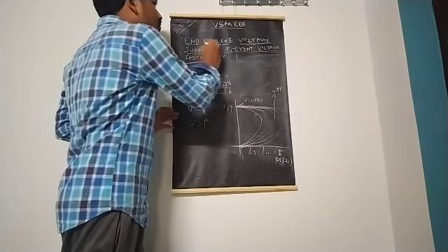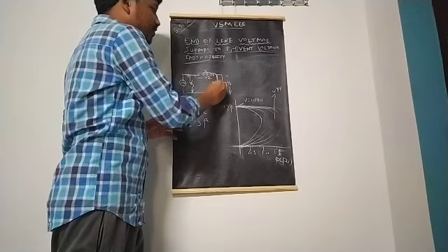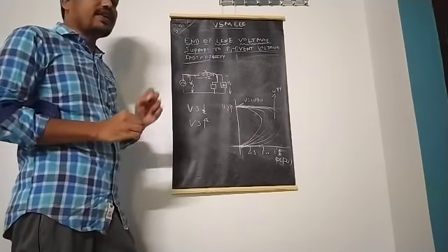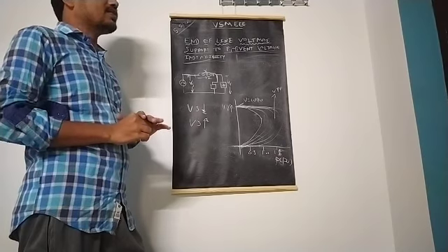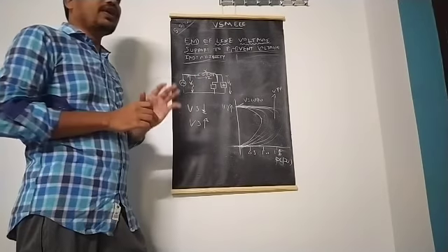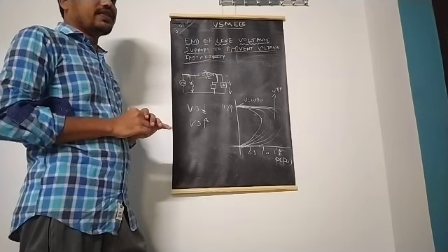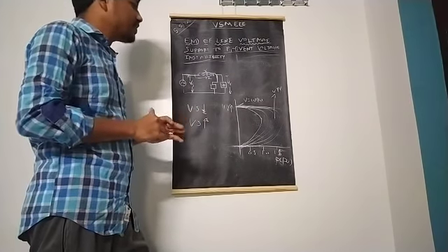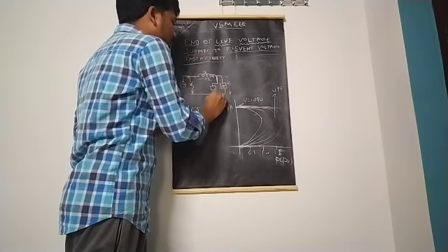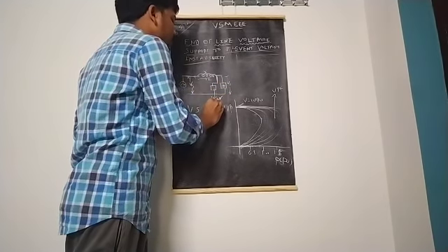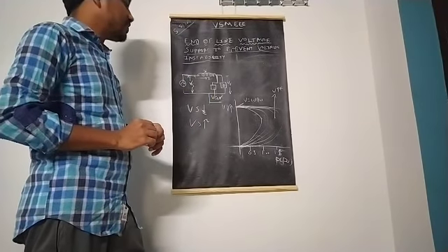So here the end of the line voltage support is very helpful in case of radial line systems. In case of a radial line system, the receiving end voltage is very low, so many disturbances occur at the receiving end side. That's why we are connecting one compensation device, or VAR compensation device, or shunt compensation device near to the load. This is nothing but the VAR compensator, that is, a reactive power compensation device.